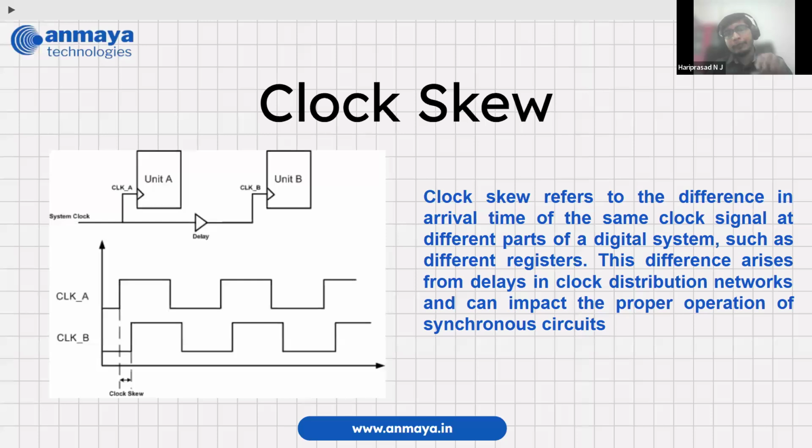From there we generate and get some base clock, let's say 100 megahertz or 50 megahertz. But for my application, usually in 5G applications, we use some standard clock, which is a multiple of the base clock. It will be I think 122 point some value. This clock we usually generate using PLL. And this whole clock goes through the dedicated clock path. We usually call it global clock routing. But whenever I ask somebody to divide the clock, how do you divide the clock?